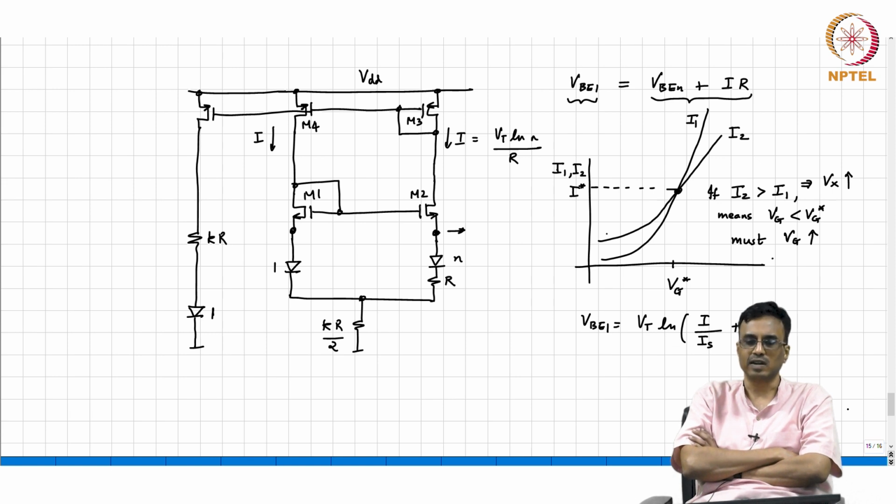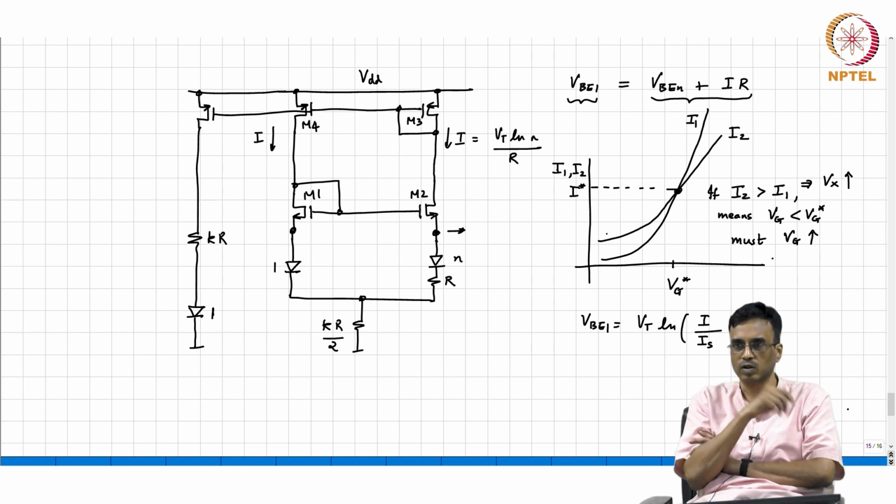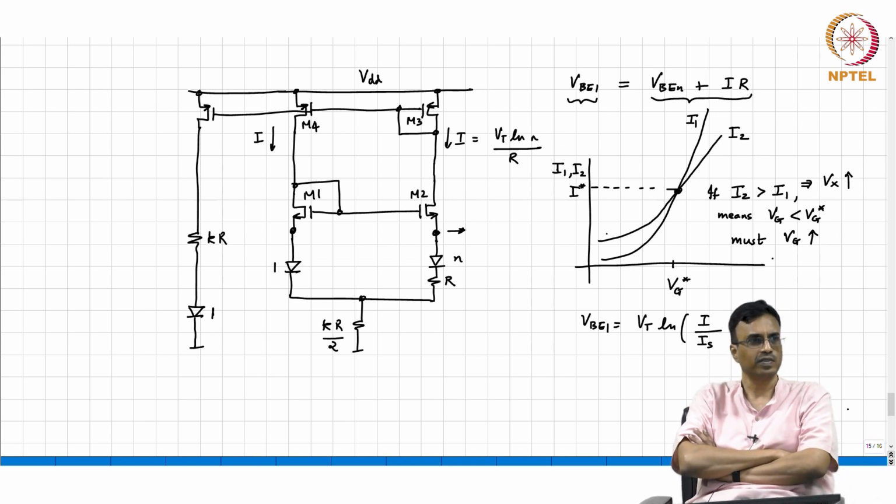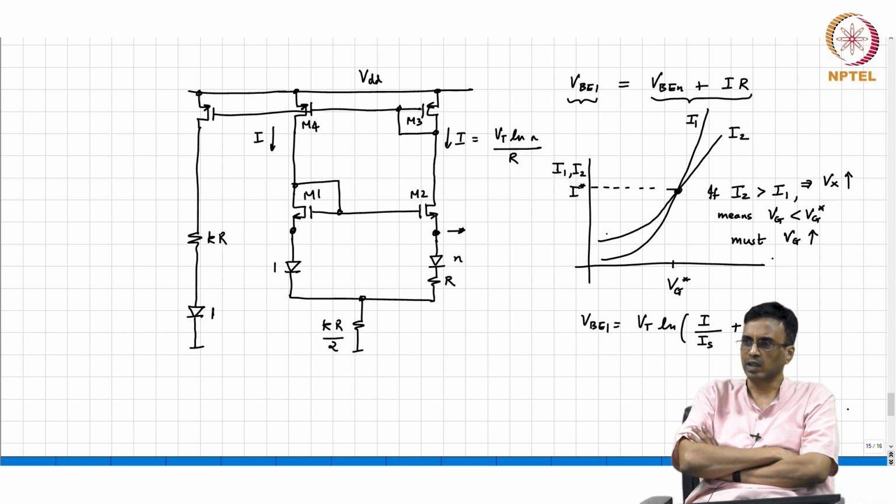And these circuits are actually very deceptive, right? So it's very easy to make a mistake, correct? If you don't understand, and you write the equations for the other circuit where you flip the mirror on the PMOS side and flip the mirror on the NMOS side, they all are the same. So you would get tricked into believing that the circuit works when in reality it does not.